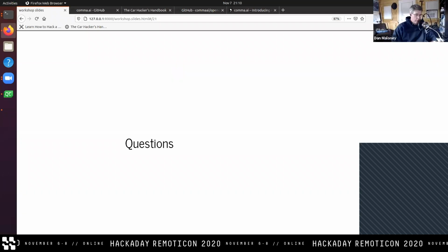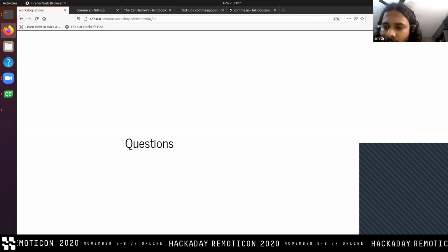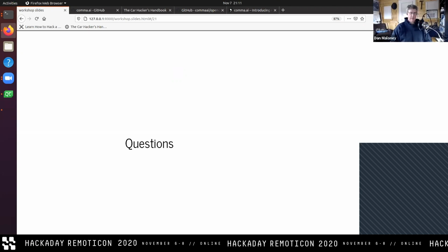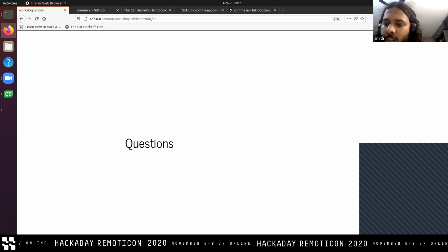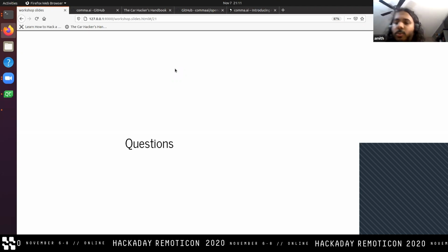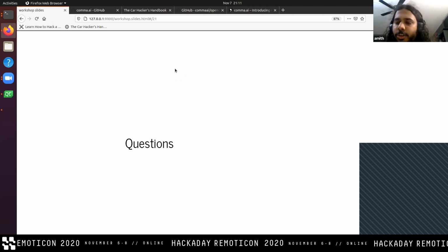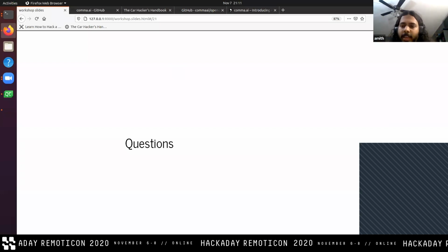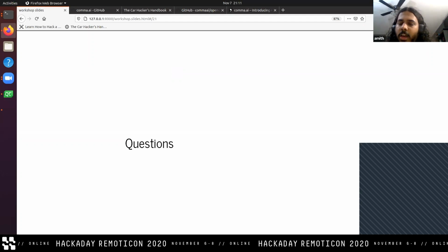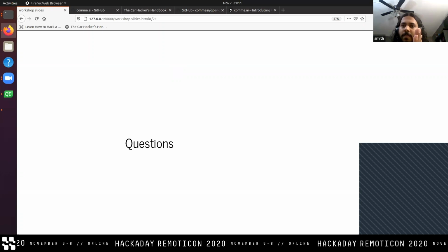There's one from Greg in the chat. Greg asks, in your experience, are current-gen cars implementing any measures specifically to prevent manipulation or injection of messages, or are the CAN buses basically a free-for-all? You know the car door trick I showed you about recording the CAN messages and playing them back? That may not work on a lot of cars, because on the OBD port they might put a firewall,